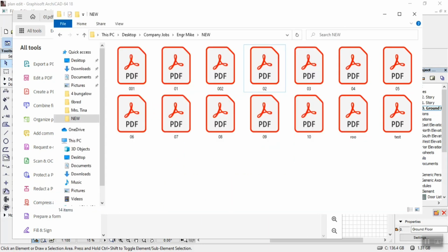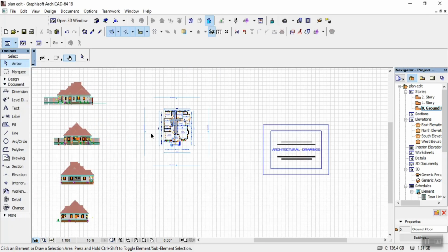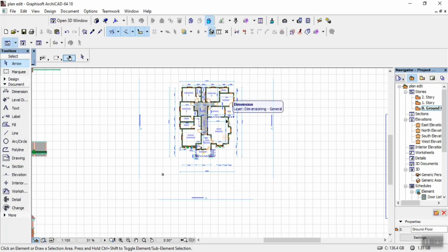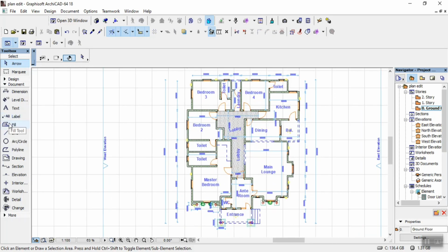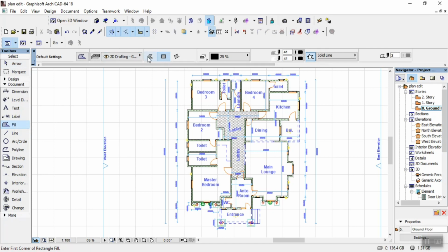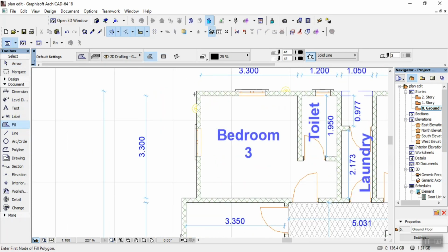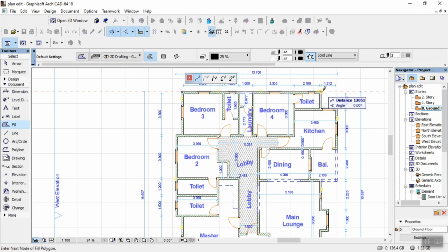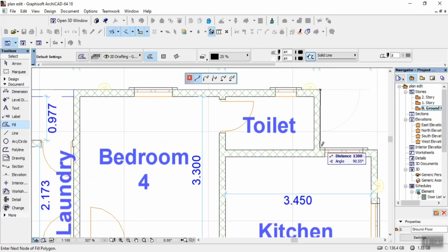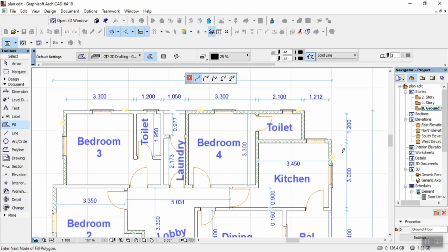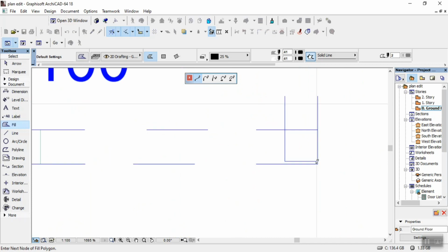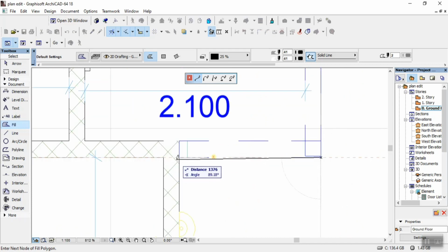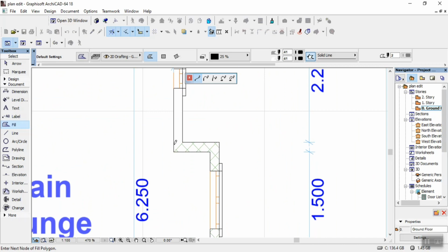So first we'll come back here for you to get your site analysis, because this is the building. Now let's assume the client gives me a land size of 30 meter by 15 meter. I'm going to come to that. First, for you to get your site analysis, you come to your field tools, you pick your polygonal line, you trace this. You have to trace your design from all edges, carefully. You can see the way I'm tracing mine. You have to trace it from all ends, don't make mistakes.